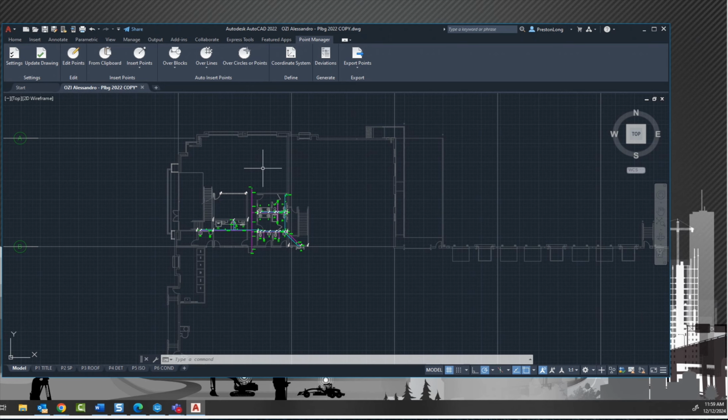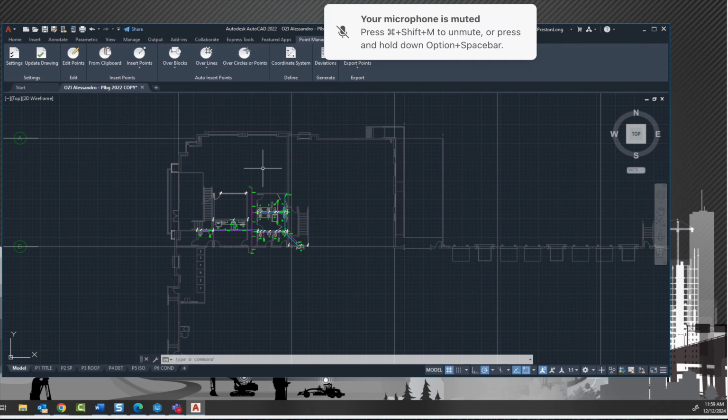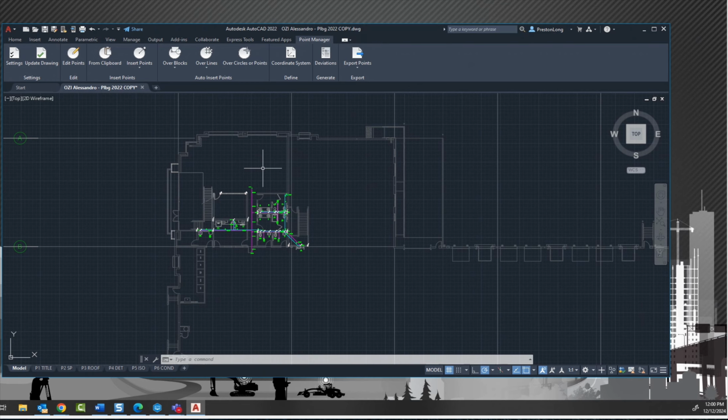So if there's going to be a 4 foot offset, you need to make sure that those lines in the CAD file have that 4 foot offset. If you're going to use lines, if you're going to use points, and this is what I usually tell everybody, if you go out there and do a 4 foot offset grid line layout, each one of those intersections is an actual point, right? So you could set up on one of those intersections, backside to another one of those intersections, and you're set up and ready to go. But they just have to match. Right.